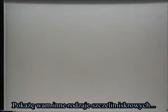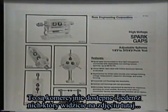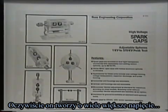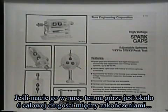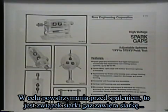Okay, I'll show you some other kinds of spark gaps. These are commercially available, and the ones that you're seeing in the illustration there go to about 370,000 volts. And of course they make them for much higher voltage. If you had a ruler on there, the top one is probably about 6 inches long from one end to the other, and you have to pressurize these things and put a gas inside them in order to keep them from burning up.